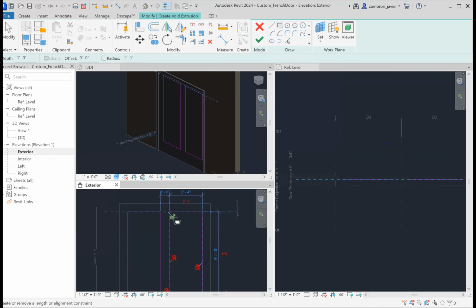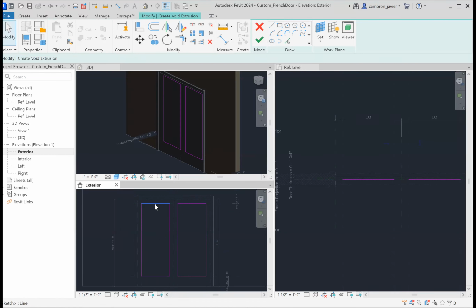So let's go ahead and make sure we hit these lock pads. But this one here, you know what I'm going to do? Instead of having to hit a line and do that whole clicking, double clicking everything, aligning everything, then clicking the lock pad, I'm actually just going to place my cursor. I'm not sure if you guys remember, I think it was the roofing, we place the cursor and then hit the Tab key on the keyboard and it selects everything that is connected to each other. I'm just going to delete this and we'll start over. I think this might be faster. There we go. And now let's hit the lock pad.